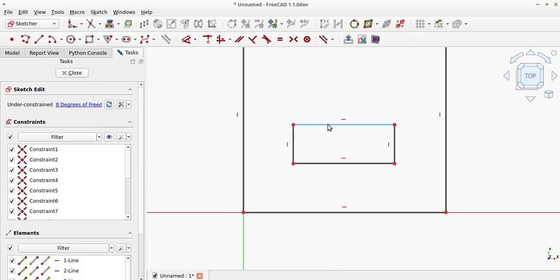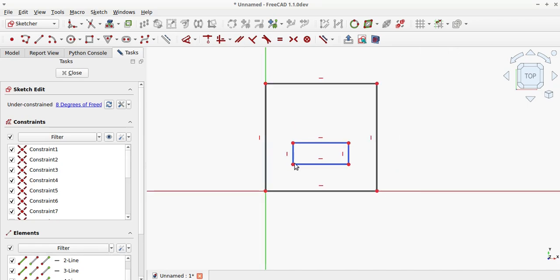To create a double dowel imitating two domino dowels, I will convert the original tenon pattern to construction lines and draw two rounded dowel shapes. Of course, you can draw anything here and all connections will be updated with the new pattern.